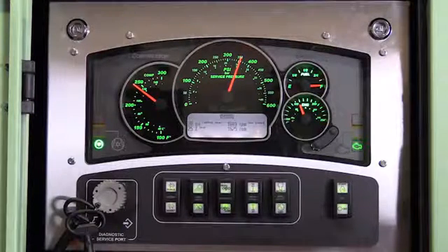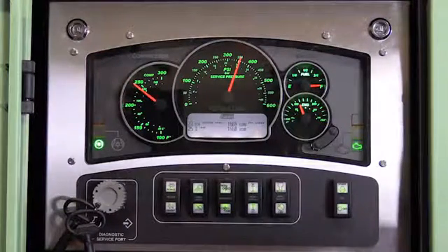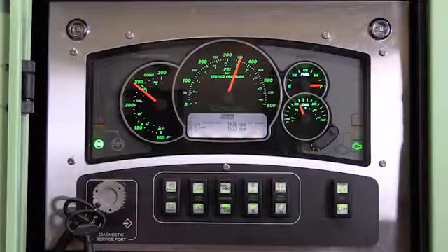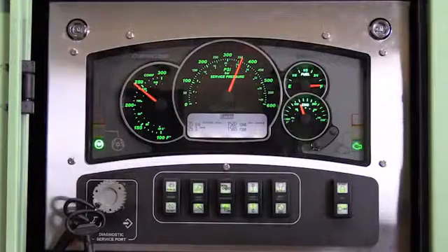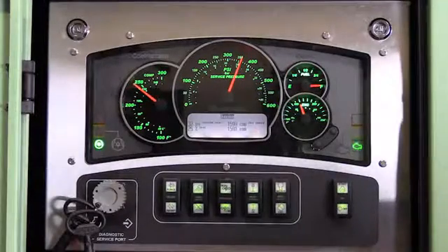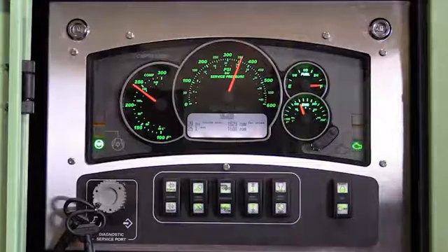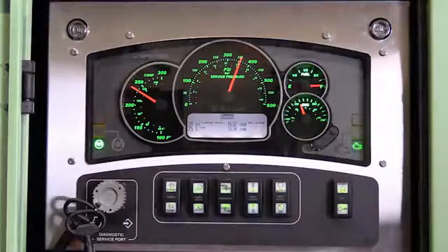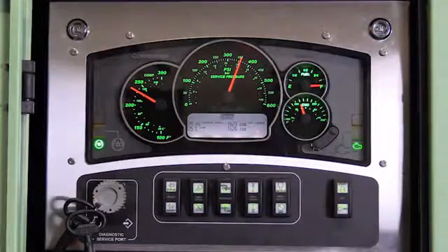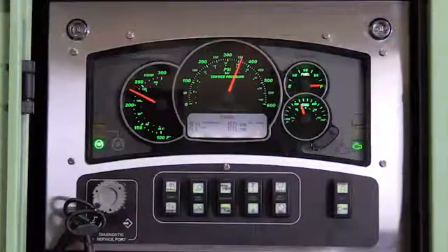If regeneration is not desired, the automatic regeneration process can be halted by engaging the Regen switch to the inhibit position. If the regeneration is inhibited, the DPF inhibited lamp on the controller screen should be lit. Regeneration inhibition should not be a regular practice, as allowing soot load percentages to get above 116% could cause the unit to abnormally shut down and fault the DPF. The unit will not be able to function until the faulted DPF is replaced.